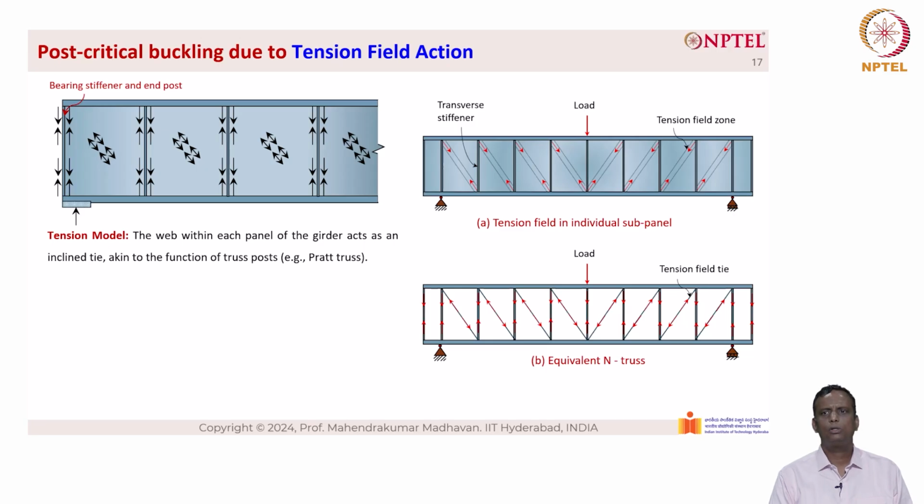This is equivalent to what is known as an end truss. As you can see that there is an end truss here. The chord here is basically the tension band that is taking place. You can see that the arrow marks are away and the compression band is basically kept empty because the compression does not take any load and the vertical stiffeners act as a post.